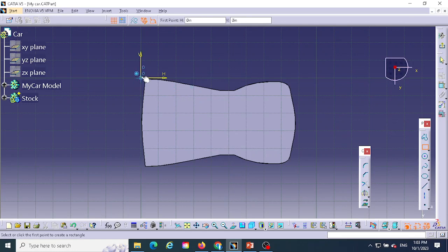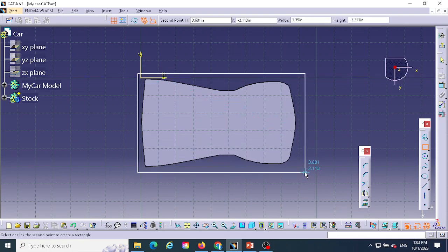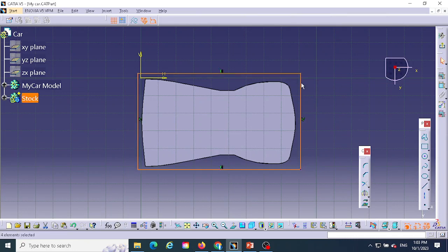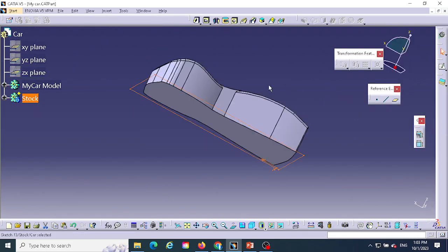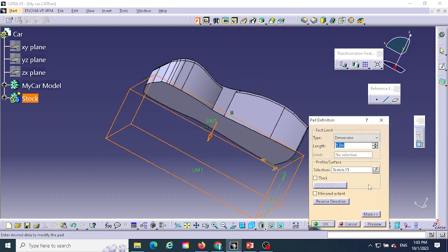Again, we can have the part, create such stock. So the base, you can have such a thing. This is the base. Having this base size, you can approximate. It depends on what stock you have, but I just chose this size so that the actual part is at the middle, at the center. I skip the sketch workbench and go to the modeling window.